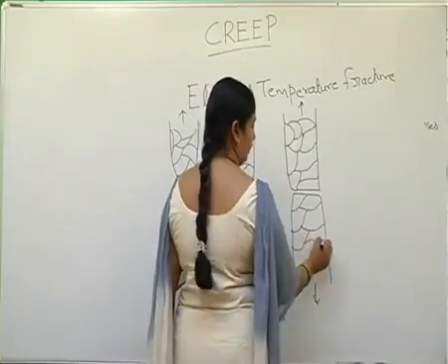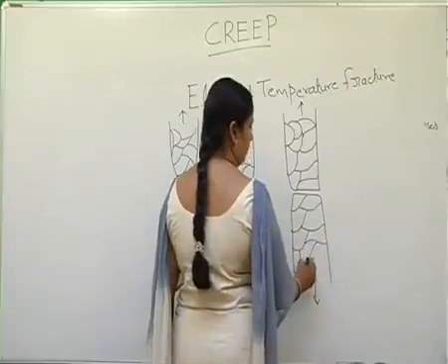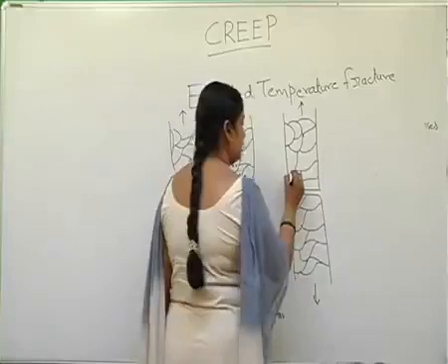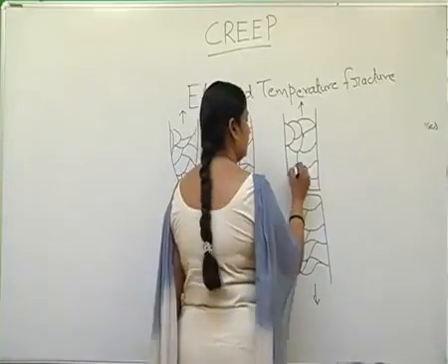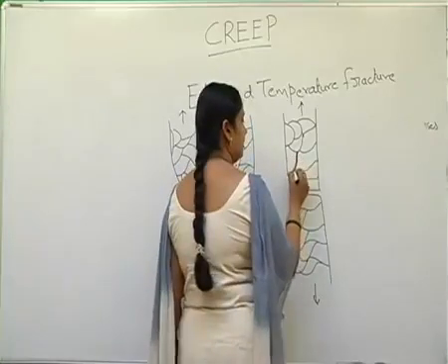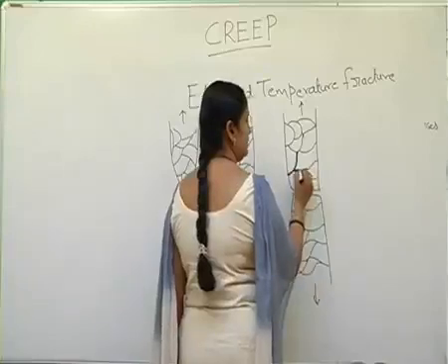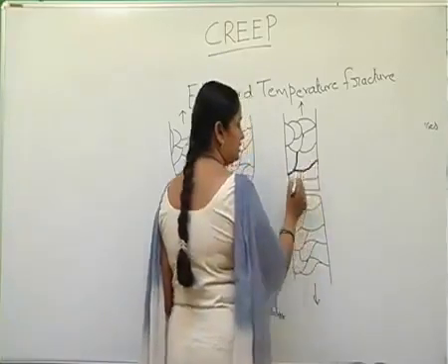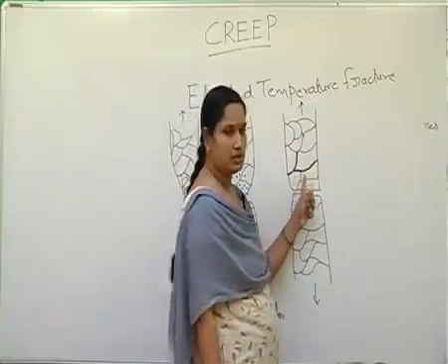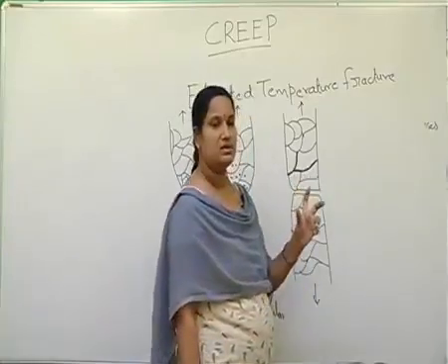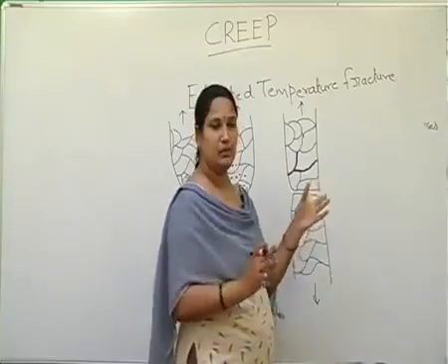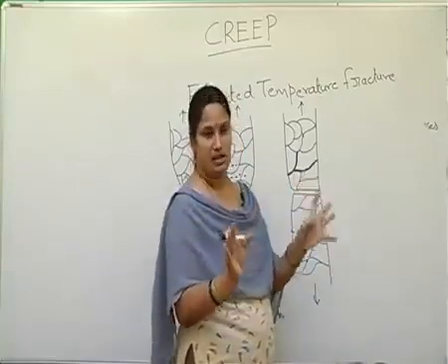So the formation and growth of voids all take place at the grain boundaries. So the grains separate at the grain boundaries, and this is a type of brittle fracture. The voids nucleate at the grain boundaries, they grow and coalesce to form a crack, and then the crack propagates along the grain boundaries and separation takes place.